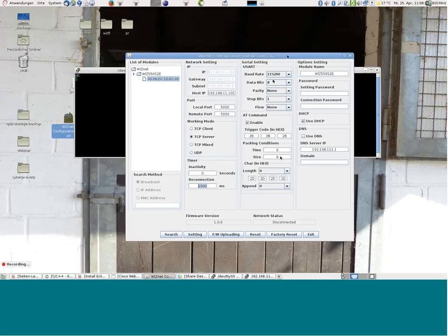Of course, the serial interface needs a configuration of the baud rate. We support 7 and 8-bit. We support odd, even and no parity. We have 1 and 2 stop bits. We have flow control, hardware flow control for RS422 bidirectional and RS485 unidirectional control.